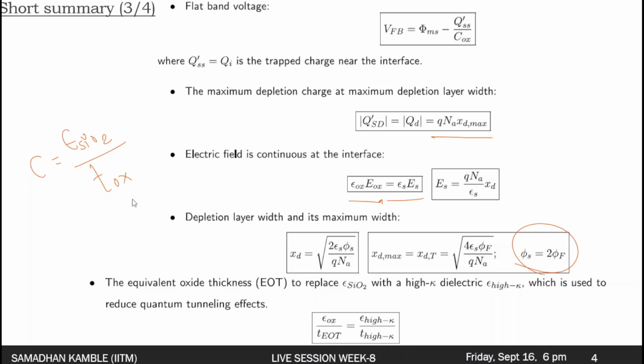In technological terms, we say that we are using 6 nanometer technology, 10 nanometer technology, but it basically refers to the thickness of the oxide material, or the insulator that is used in the MOS capacitor. However, there is a limit, and that is because of the quantum tunneling that happens when the Tox becomes fairly small, and that leakage is not ideal for our MOSCAP functioning.